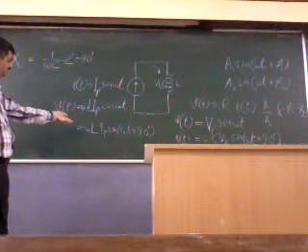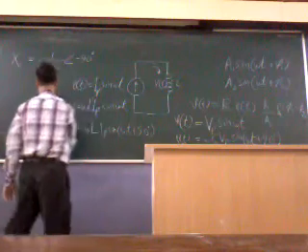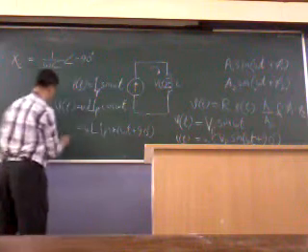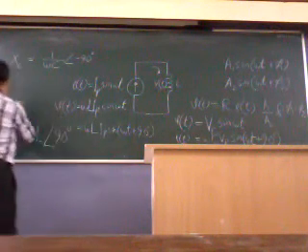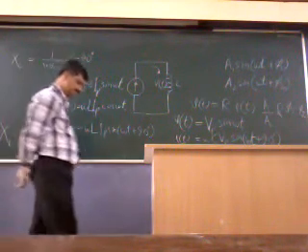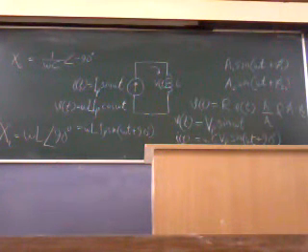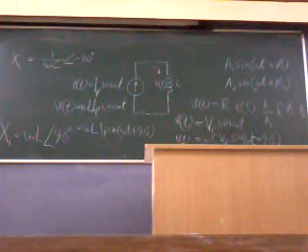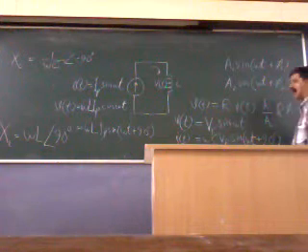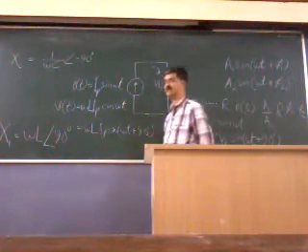The ratio of amplitudes is to be taken, that is omega L, and the difference of phase, that is 90 minus 0. It is XL. The impedance of the inductor is omega L and angle 90. Impedance of the capacitor is 1 upon omega C and angle minus 90. And impedance of the resistor is R and angle 0.